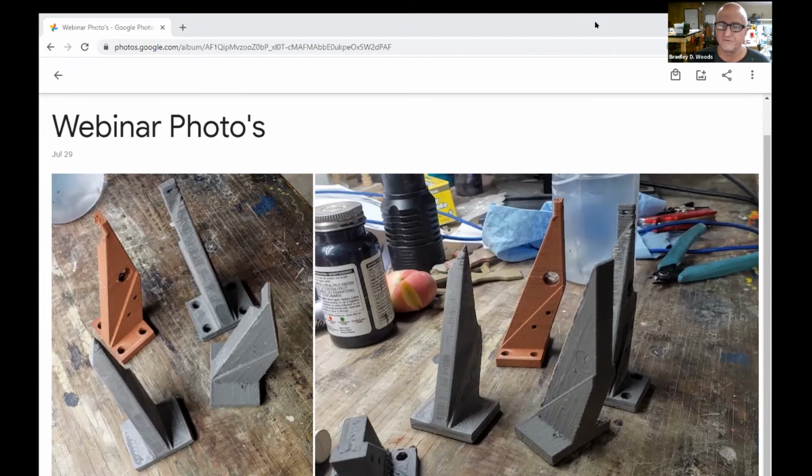I mean, it's good enough for infill, but it isn't good enough to sinter, and it'll tend to collapse. Right. If you dig around a little bit and use a different infill pattern, rather than the bicubic where it's at a 45-degree angle, use vertical lines. And we've sintered parts all the way down to no infill, depending on the size. You can print a hollow part, and you can print things with internal cooling channels and such.